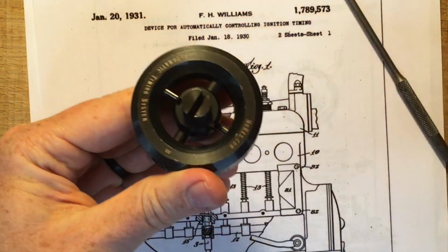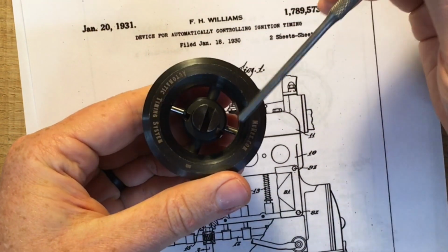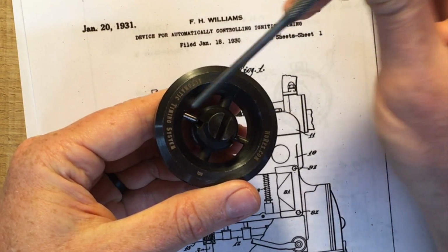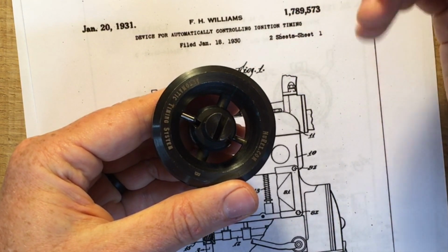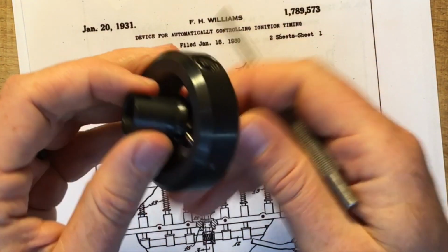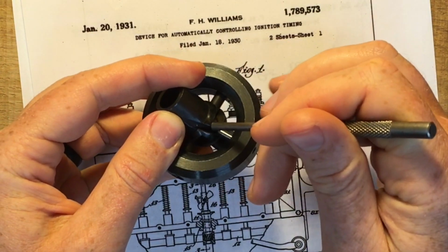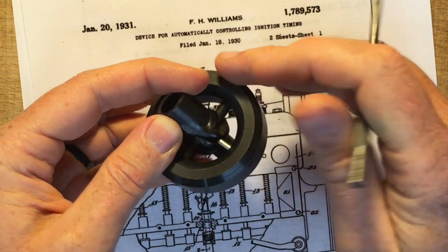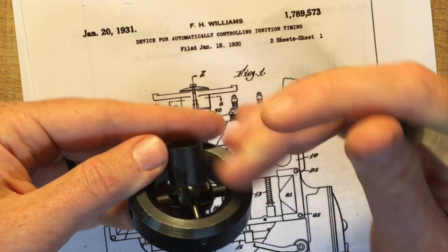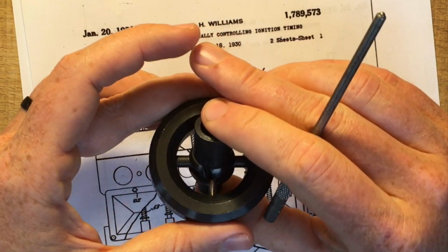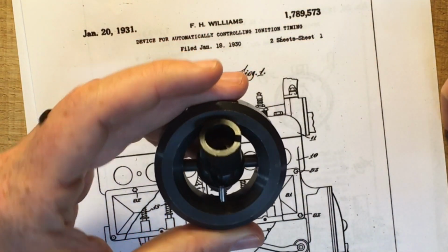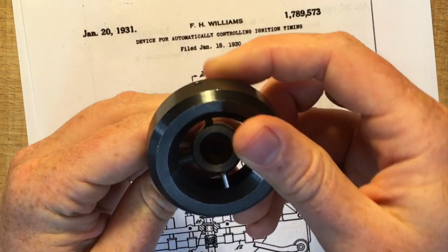these drive pins, one, two drive pins right here. I'm sorry, guide pins, rotates these guide pins in relation to this collar, the slotted collar, which is attached to the upper shaft. Now, the slots on this collar are slanted, so as the guide pins move, the upper shaft is rotated relative to the lower shaft. Let's see if you can see it here.